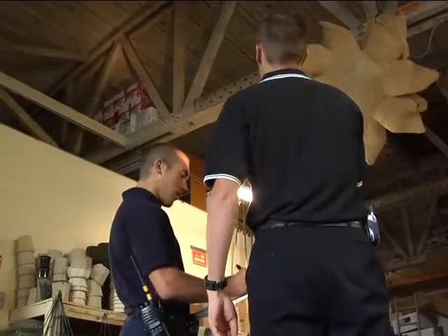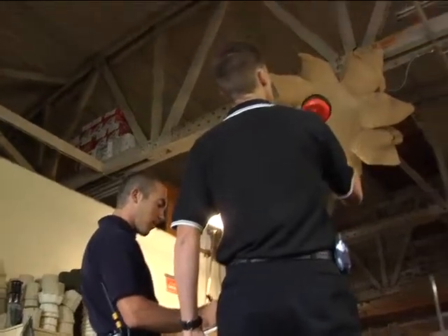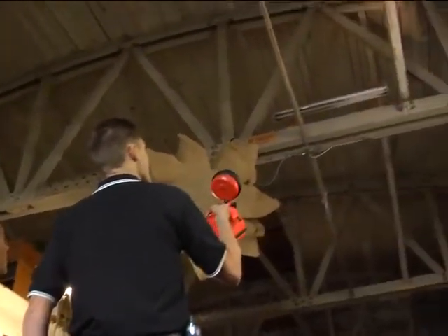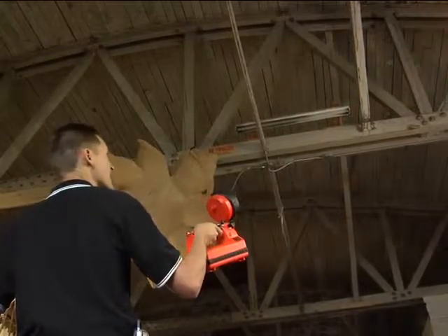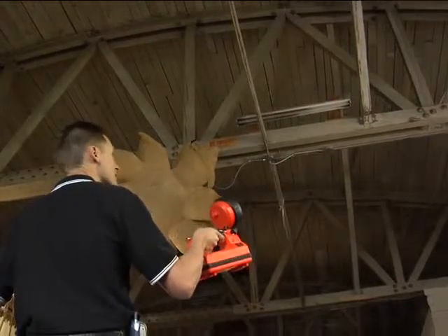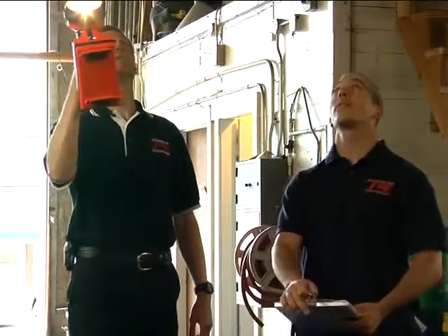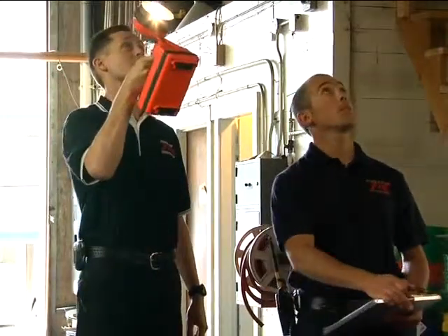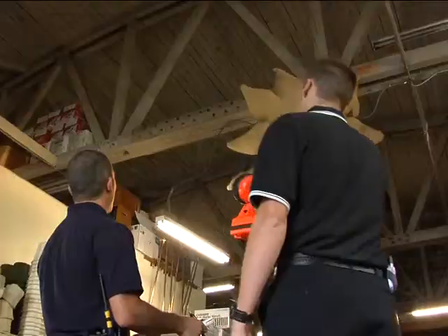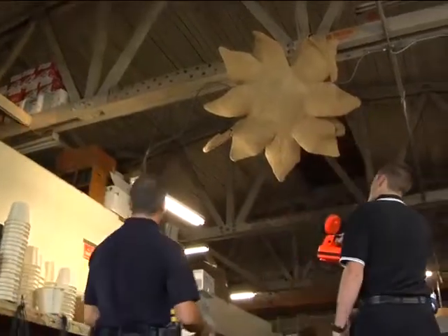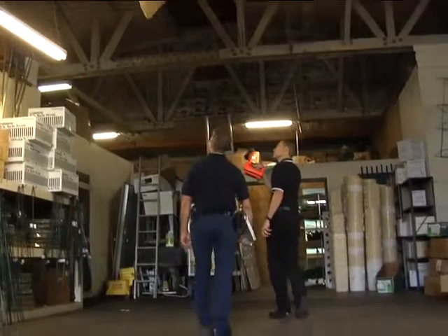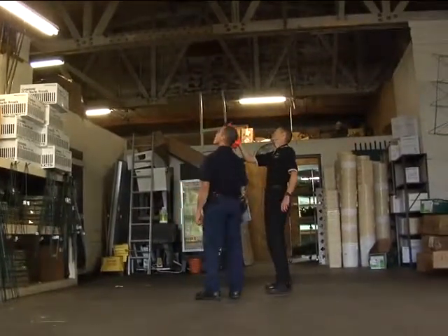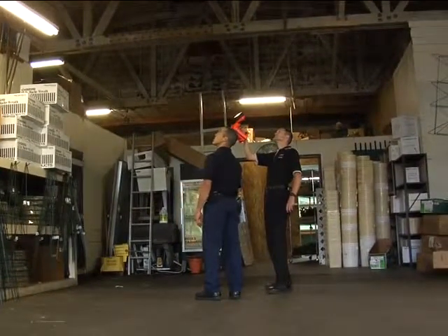First, the type of roof construction is important in judging the roof integrity in a fire situation. Pre-incident inspections and plans can provide valuable information about buildings that have bowstring trusses or lightweight wooden trusses. These types of roofs may fail early in a fire and with no warning. They are extremely dangerous to be working on or under.